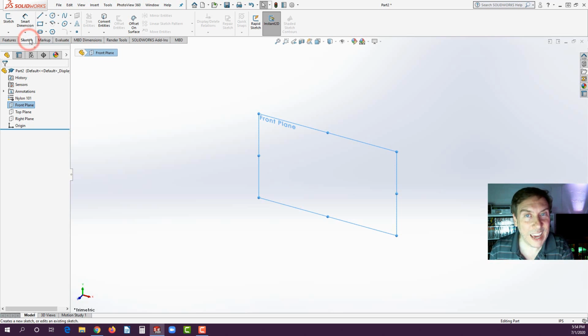You go to the Sketch tab, and I want you to just hit the little arrow underneath Sketch. You'll see there's 3 options. There's Sketch, 3D Sketch, and 3D Sketch on plane. Note that 3D sketches, as I said earlier, aren't covered until the 9th week, which is exercise 7. If you want to see how 3D sketches work, go there. It's great for piping, for tubing, for structural steel, things like that.